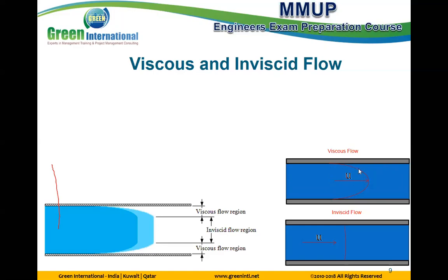It's called viscous flow. You see the velocity profile: maximum at the center, decreasing going up and going down, because this is a tube. A tube means the walls are stationary. This is different from the example we solved last session: a stationary plate below and a moving plate above, so the minimum is below and the maximum above. Here, in a tube, the maximum is at the center and at the walls it is zero.